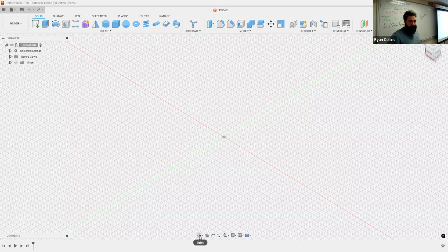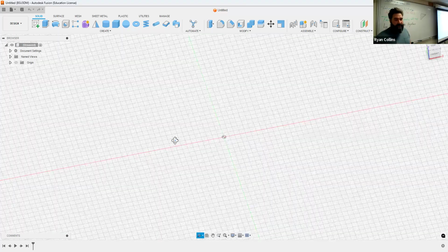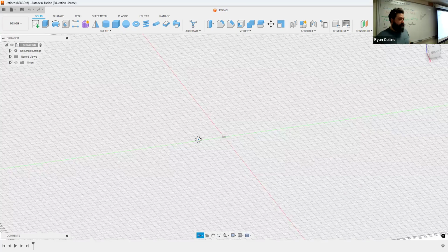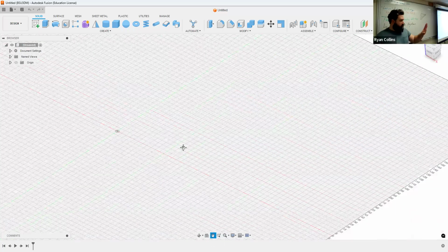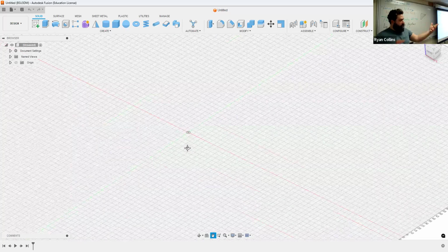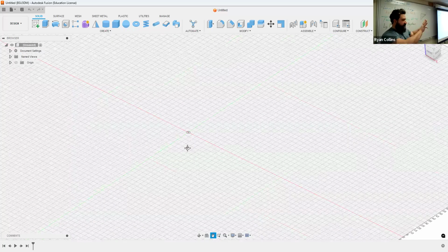So you have orbit, click that, and you have the little symbol for moving around and around. Click and hold, click and drag, and you can see how you orbit around. Hit escape to get out of the tool. Look at, you have to have an object to look at it first. The little hand symbol, pan, left, right, up, down. Orbit, rotate, pan, just sliding it around on your screen.